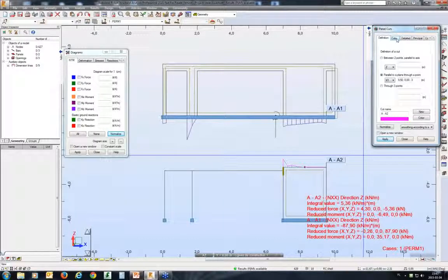If you want to see the results at the edge parts of the shear wall as diagrams for bars, then you should introduce the bar elements at the edges of the shear wall. It's really either or, and the question is what kind of results you want to obtain and what you want to do with these elements.